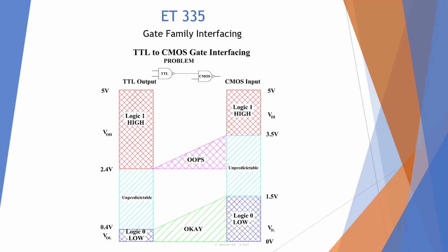However, if we go in the opposite direction, TTL to CMOS, it will not work because our noise margins are out of sync. So this one has a very large output, but our CMOS will not accept it. So there's a lot of cases that these will not work. So we never connect TTL to standard CMOS.